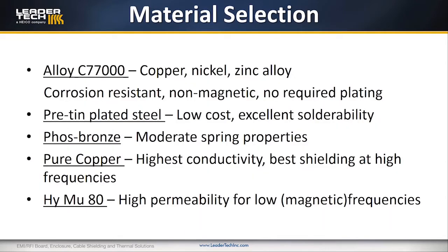When we're designing an EMI shield, the first aspect that you look at is what type of material you're going to make the shield out of. So you have to ask yourself, how is the shield going to be used? Will it be in a corrosive environment outside, in a vehicle maybe, or is it going to be indoors in a protected environment? So we have multiple options of material.